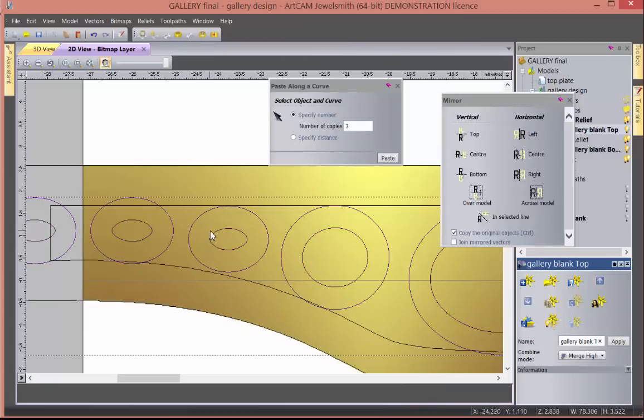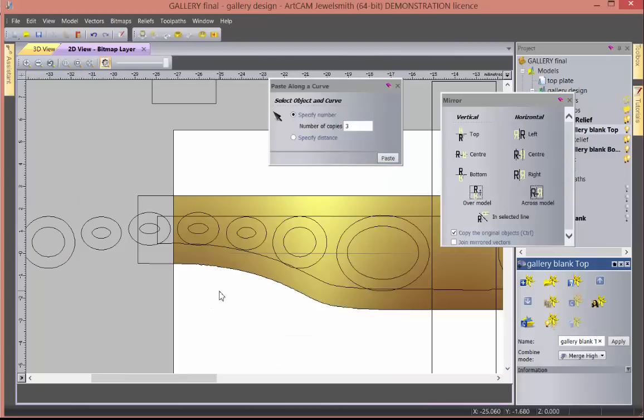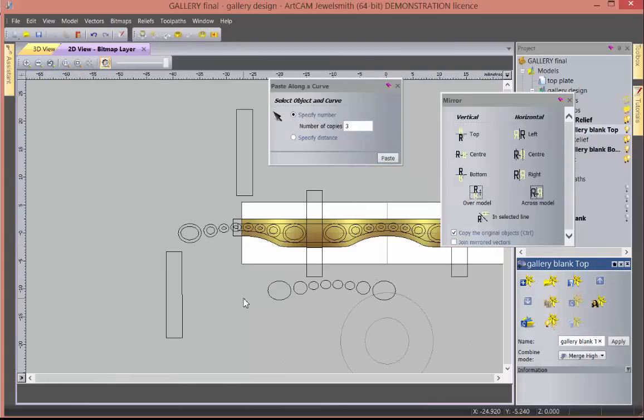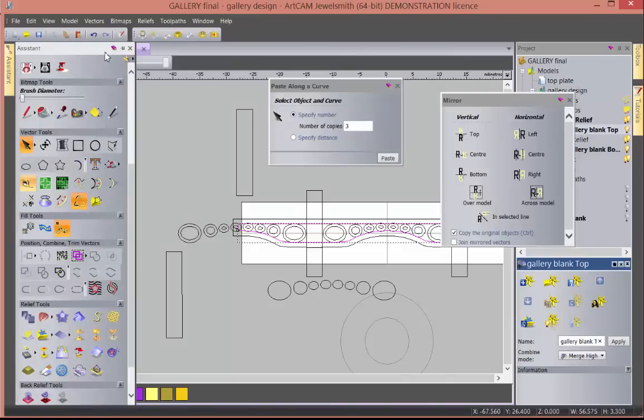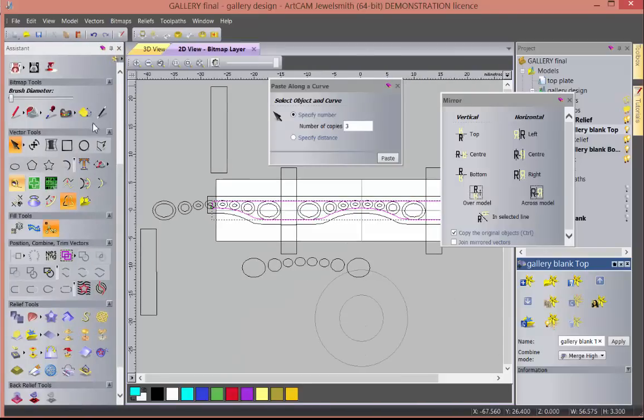This could have been a tad larger, but you guys, in order to save time, I would have actually made this one a fraction bigger. But all right, so here we go. We are ready now to remove this area. So we're going to use, a color will be the best thing for us to use. So we're going to select all of that. To bring up the color, we have to turn off the preview layer. So we bring up our color, and now we're going to flood fill. So I'm going to lock it now, for now. So we're going to flood fill that blue.